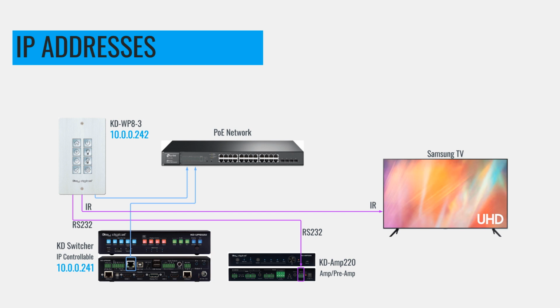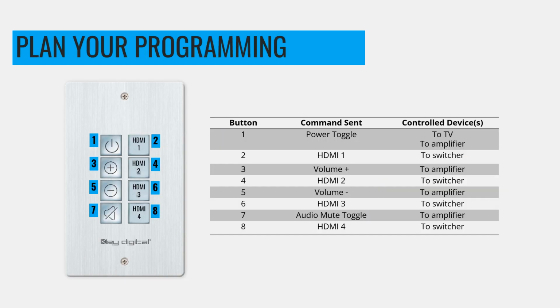The presentation switch will be controlled via IP, and we've gone ahead and mapped out our IP addresses for the keypad and switch: 10.0.0.242 and 241 respectively. Additionally, you really must plan your programming. What do you want to happen when you press each button?